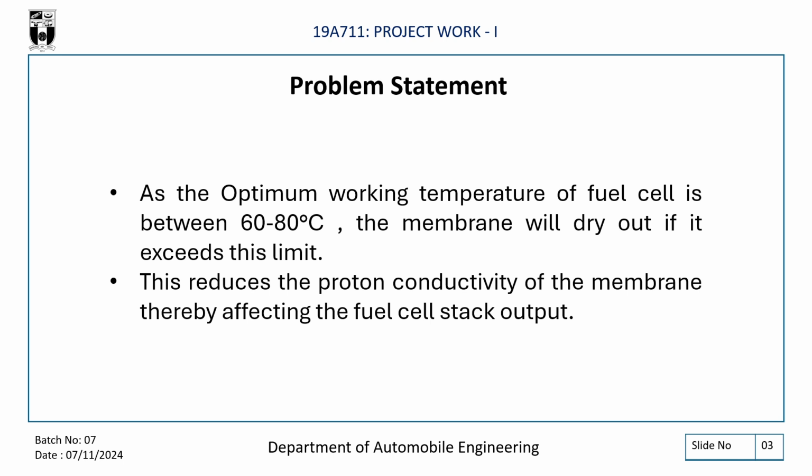Next, the problem statement. As the optimum working temperature of the fuel cell is between 60 to 80 degrees Celsius, the membrane will dry out if it exceeds this limit. This reduces the proton conductivity of the membrane, thereby affecting the fuel cell stack output.